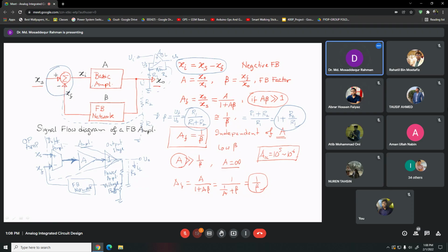Inside the op-amp itself you have another buffer, but the op-amp we are using as an amplifier, but we can also use it as a buffer if we want to transfer a voltage signal from one circuit to another circuit. Then you connect the op-amp so that it works as just a voltage buffer with gain 1. Is that clear? Yes, sir.